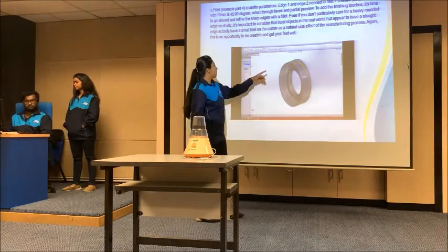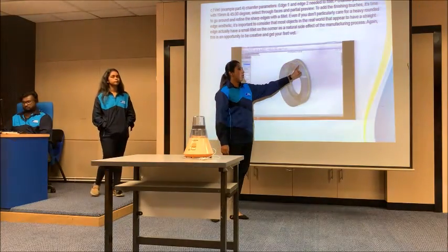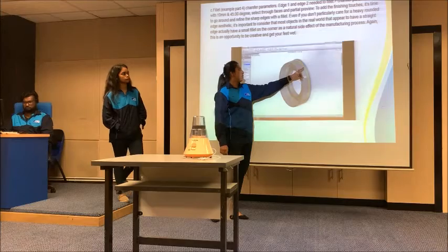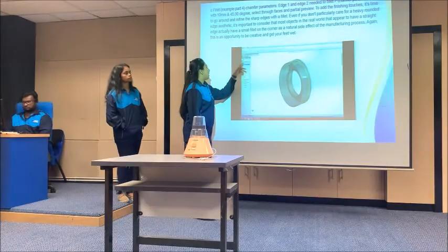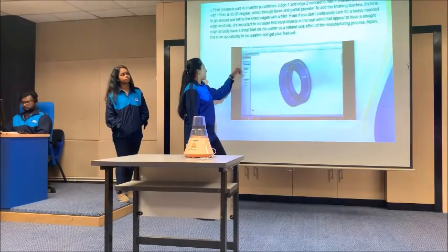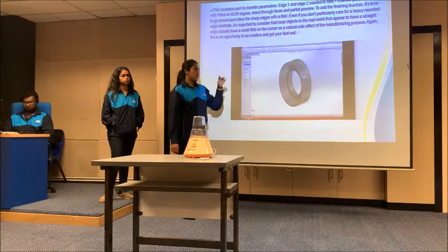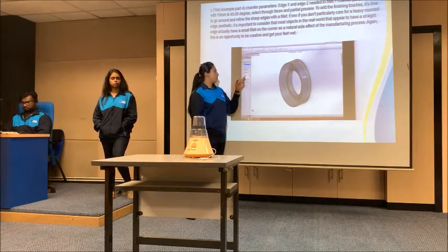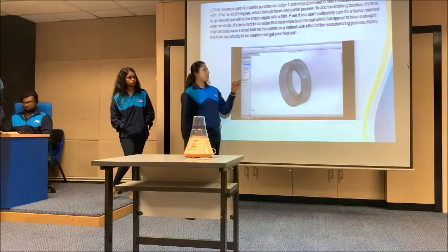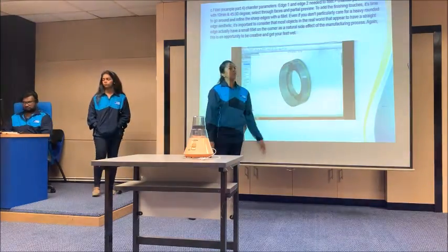That means we have to select our edge, and then maybe if you have a second option, you have to select your face, and then you have to fillet the edge and face with your fillet dimension. That means radius, maybe a 10 radius, and with the 45 degrees over here we use 45 degrees. So this is the whole procedure for fillet.